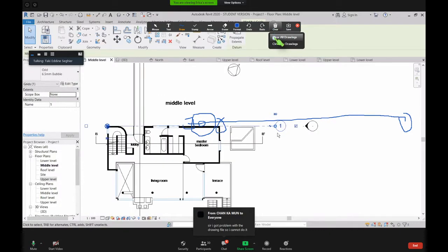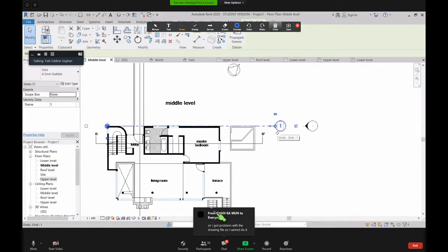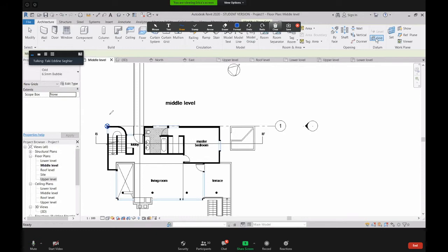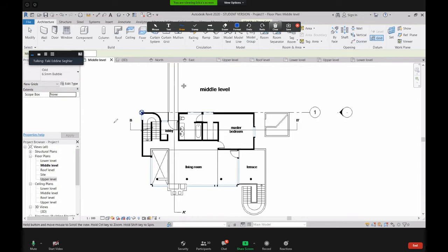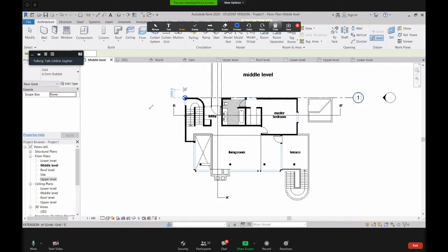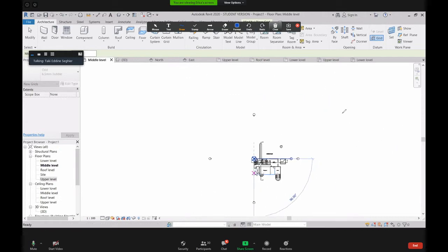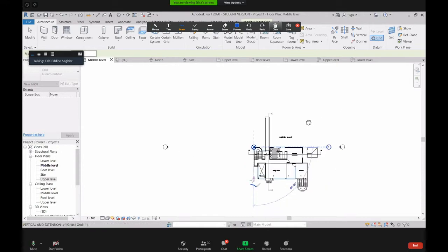Now you have to create the second one, the vertical grid, because we want to get the intersection. When we get the intersection here, I know that is the project base point, which means I go to the lower level, I will find it also, because the good thing of this grid is you can see it in any level. No, make it vertical. Go down maybe here.